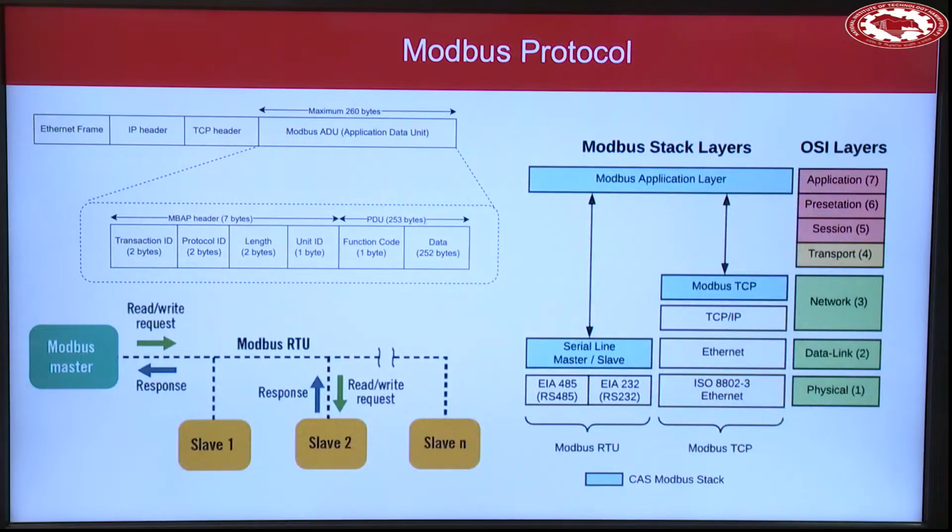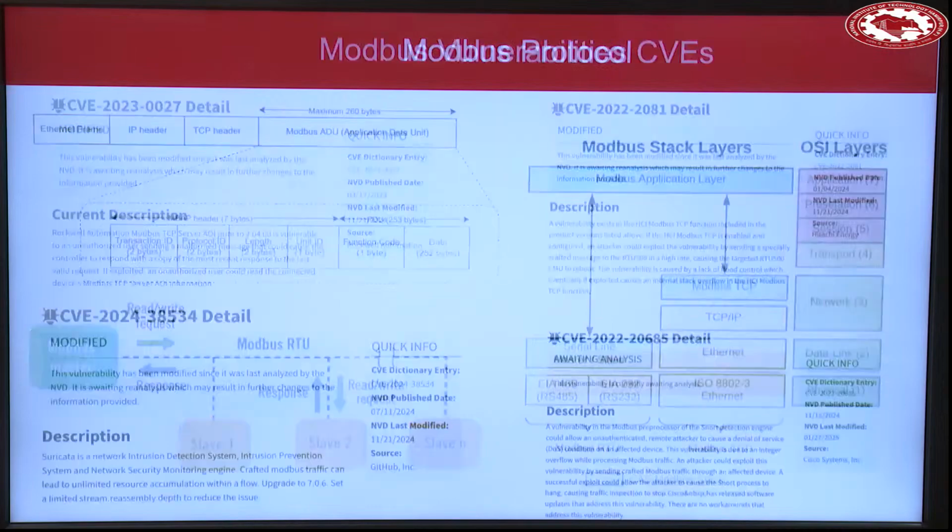Modbus, maybe you can skip all that part, but what you need to understand is that Modbus supports level 2 with serial lines, slave bus, master-slave, or it can support TCP as well. So depending on the application you are working on, you can use the Modbus protocol for layer 2 communication. There you don't need internet; a device can talk to another device directly. If you are fetching data, sending it, connecting it to the internet, you need Modbus TCP. So there are variations of the protocol.